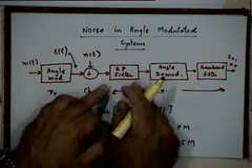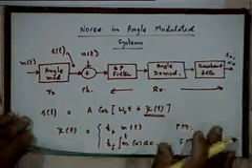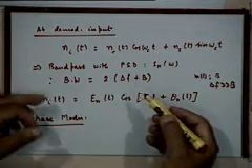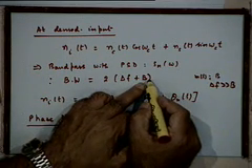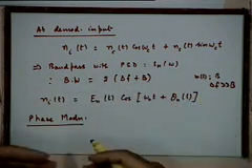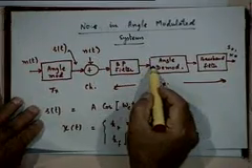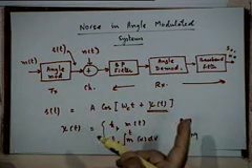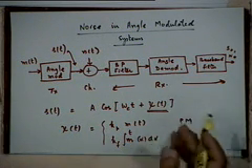So the bandwidth of this filter has to be equal to twice of delta F plus B. That's precisely the point, whereas the bandwidth of the message is B. Message signal m(t) has a bandwidth of B. The signal and noise which are going into the angle demodulator both have a bandwidth of twice delta F plus B. That's all I am saying. So I am not saying anything different from what you are saying.